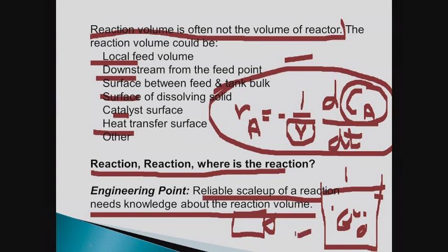Again, videotape everything. Case in point, this one scale-up, I think I've mentioned this earlier, but I'll repeat. Everything went well in the lab and went to full-scale production, and they did the first run in the plant, and all the material balled up on the impeller. Now, if they had run video studies of the reaction in the lab, they would have known that would happen.